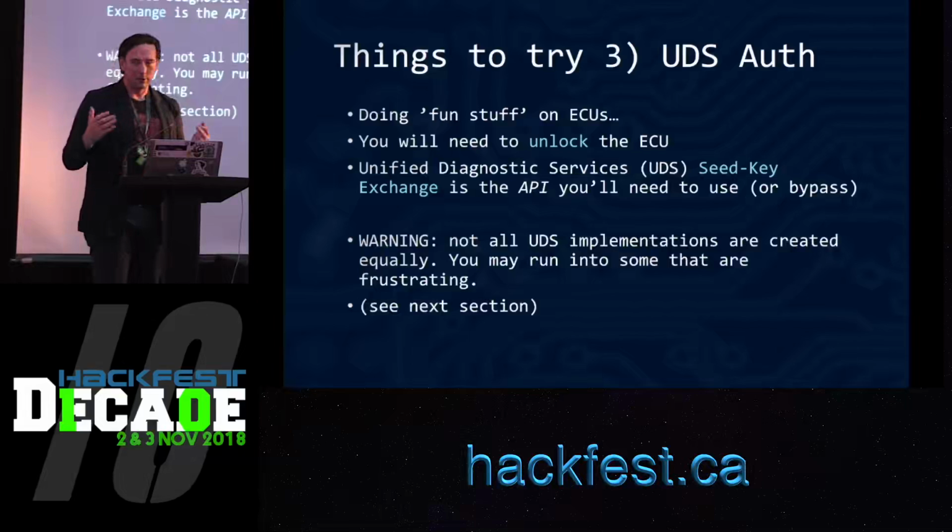Stands to reason. Okay, first up, how do you just take a binary file and load it at an address? That's actually pretty straightforward with a Radare command. There's a -m that will change the load address. So here's an invocation. I know it's ARM because we already figured that out. I know that it's thumb mode, that's what B16 means. And I know where the offset is because we read the data sheet, we did the right homework, and now we figured that out. So you can totally just load your binary in like that, and you're done.